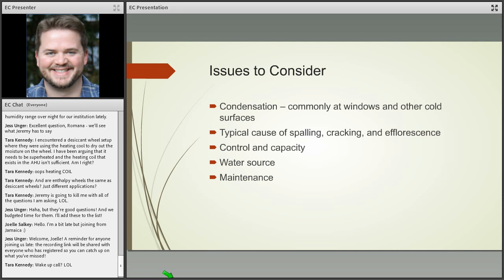One of the worst surprises that any cultural institution can have is realizing that you've moved into the summer months and summer operation and your humidifier is still leaking moisture into the airstream. It makes it awfully hard on your dehumidification system to try and maintain those right conditions.